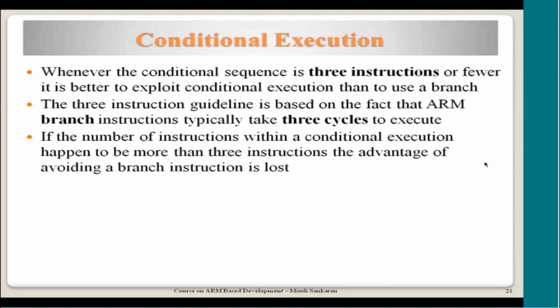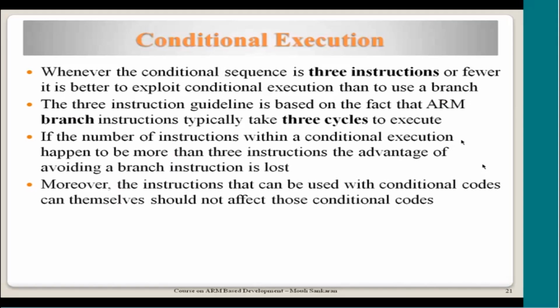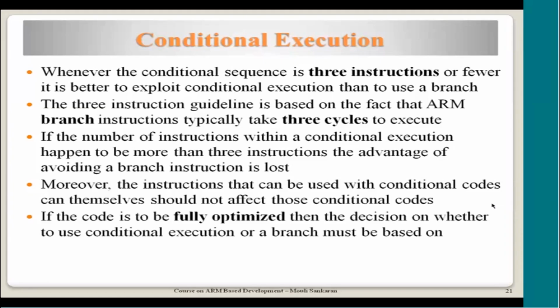And one more thing you should remember: whatever instruction you put inside the condition should not have a side effect. Though in the previous example we saw some compare instruction within the conditional execution which was intended, if you put instructions that are not intended to affect the CPSR, you may get a different result. So you have to be very careful when using conditional execution in assembly, and you should understand what happens so that you fully understand how to write assembly code here.